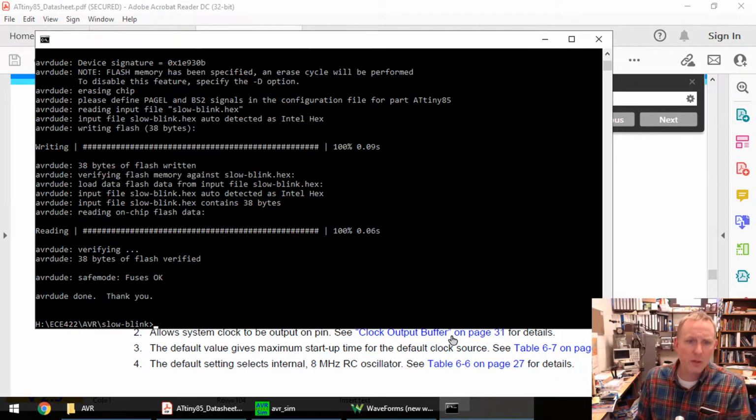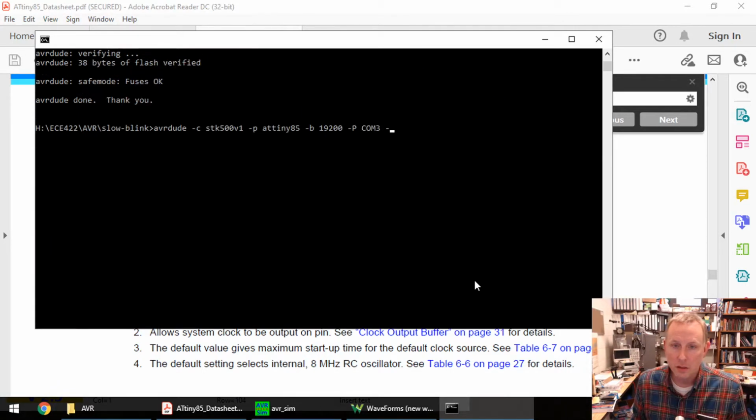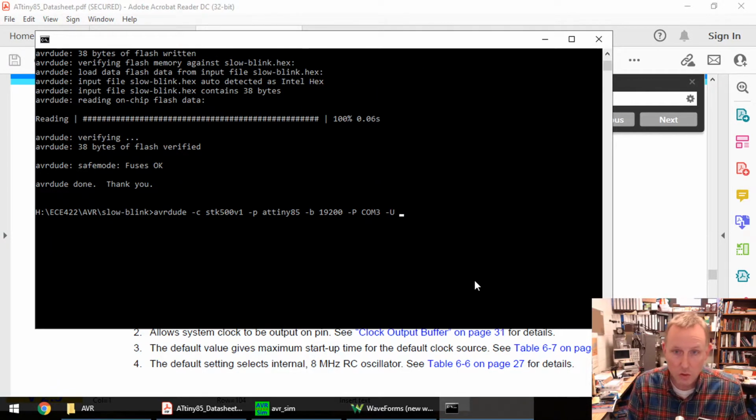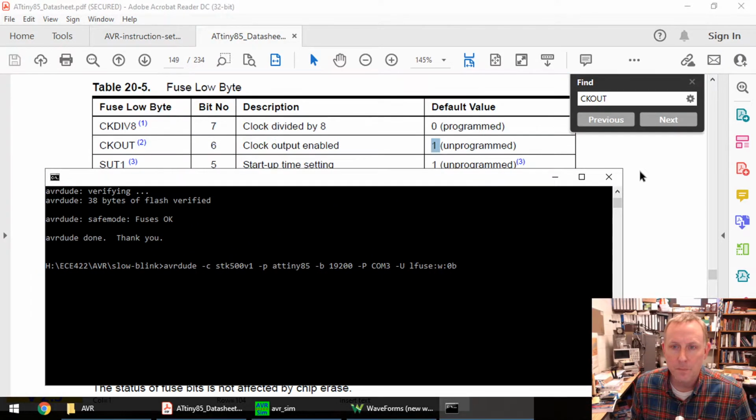Well, let's check out how we do this with AVRDUDE. So here's AVRDUDE. I am indeed hooked up to COM3, and I want to write. I want this to be the L fuse. I want to write this, and I want it to be a binary value, and do this all at the same time.